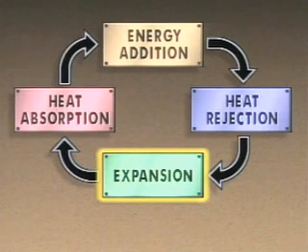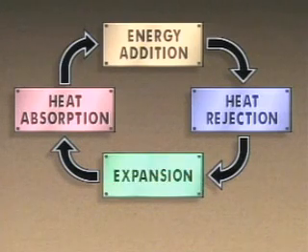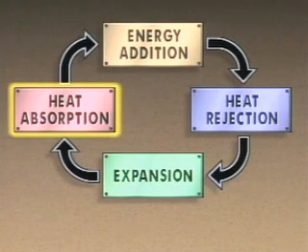In the expansion step, the liquid refrigerant is allowed to expand rapidly. This expansion causes the pressure of the liquid to drop. When the liquid's pressure drops, its temperature also drops. After the expansion step, the refrigerant is a low-pressure, low-temperature liquid. The low-pressure, low-temperature refrigerant is ready for the heat absorption step.